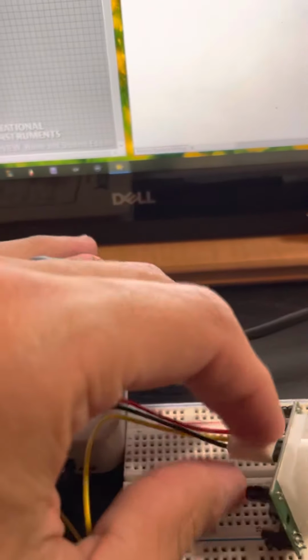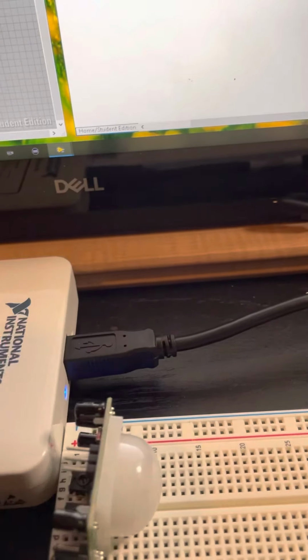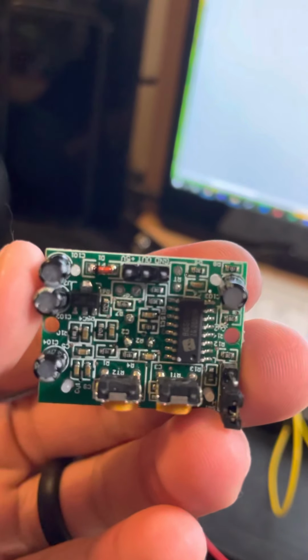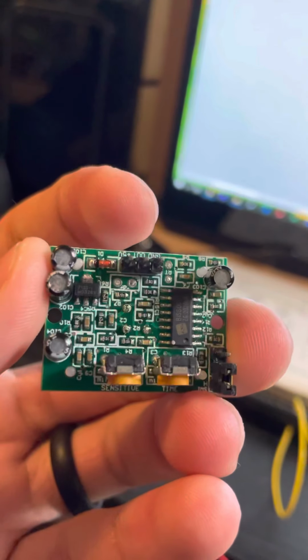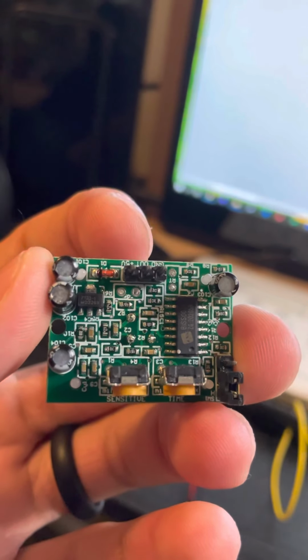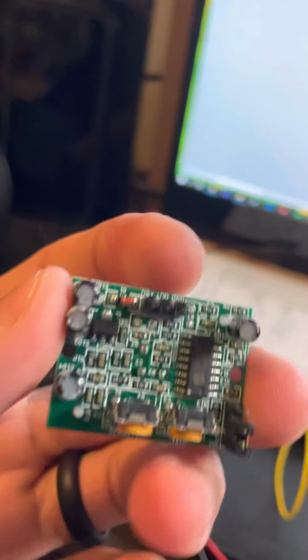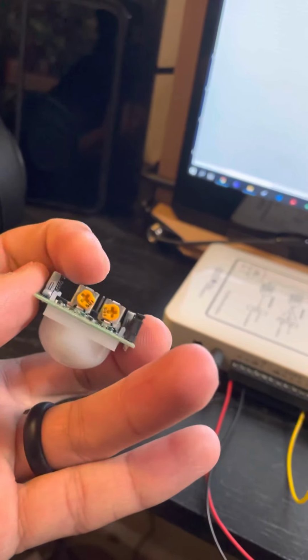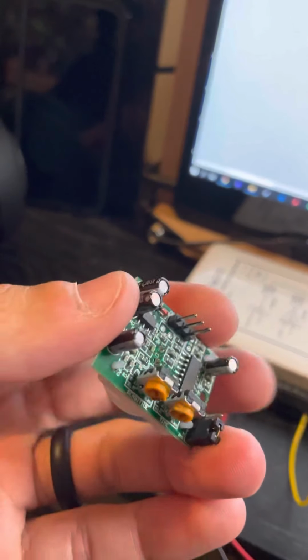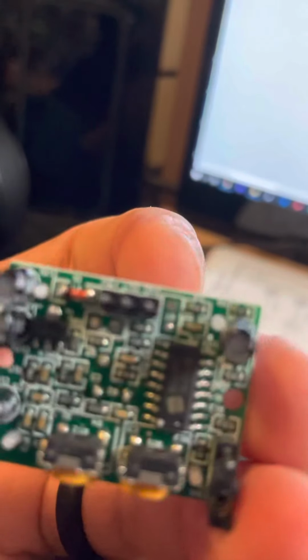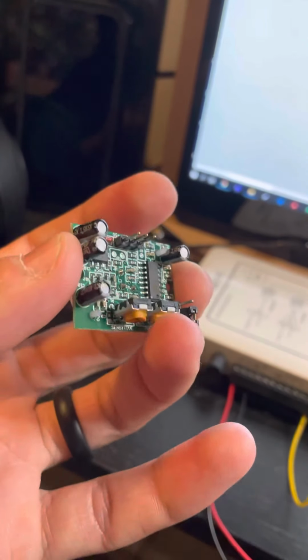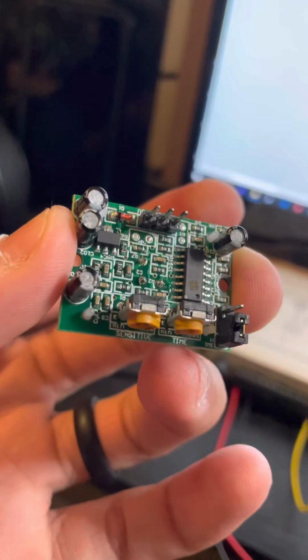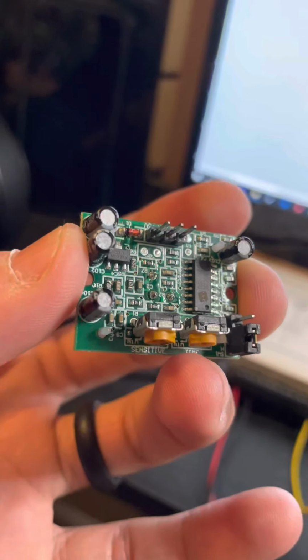Now for the motion sensor, how do you connect this? Okay, so the motion sensor, you're like, okay, how do you know how to connect those cables? But if I can focus, as you can see, that part right here has the plus 5 volts. You have your output and you got your ground. Normally when you get this kind of device, you get to adjust the resistors there, but we're not going to touch that, okay? And that's basically how to detect the motion. This is what allows the sensitivity and the timing itself, how we can adjust that, okay?